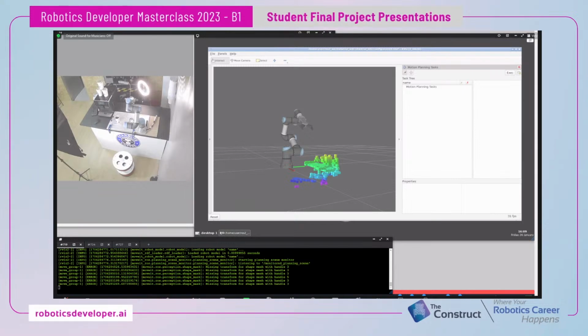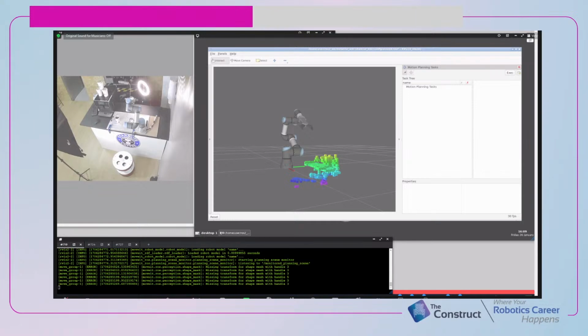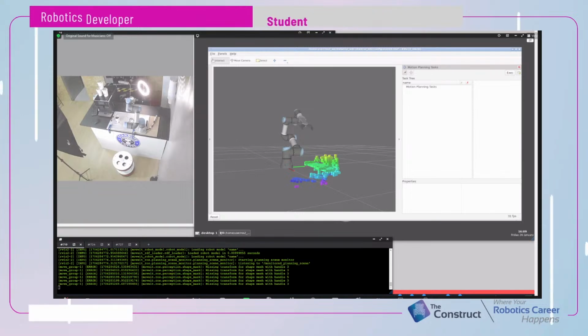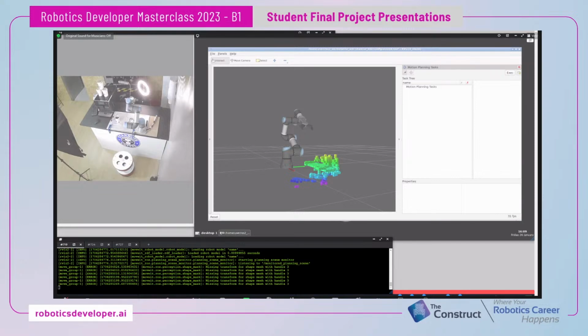Everything is from position to position. So in theory, you could go in and control the acceleration and velocity curves to add a pseudo delay, but there's no way to just say, okay, after completing this stage, wait 5 seconds to do this thing. It's waiting to see if that motion has been completed, and then it will just move on.